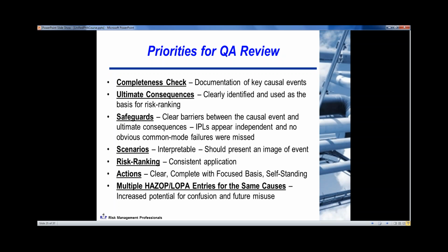So a lot of potential for confusion. And also, if somebody's trying to use the HAZOP or LOPA later, and you've got the same cause, flow control valve 001, showing up in 3 different nodes, and it's not done properly in any of the 3, and it's not synchronized, if somebody's trying to use the HAZOP or LOPA for MOC later, it can lead them to the wrong conclusion. They can make mistakes. You don't want to make mistakes, especially easily preventable ones like this, by just having discipline. You don't want to make mistakes in safety assessments.